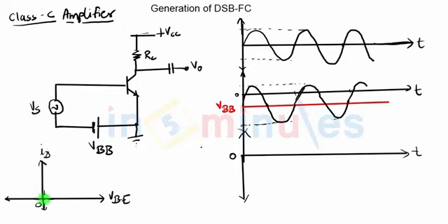And we all know that for any PN junction diode, only when the voltage across the diode crosses something called the threshold voltage or the cut-in voltage, which comes out to be 0.6 volts to 0.7 volts, let me take 0.7 volts here for silicon transistor, in that case, only when the voltage is equal to or above 0.7 volts, then the current will be flowing through the junction.